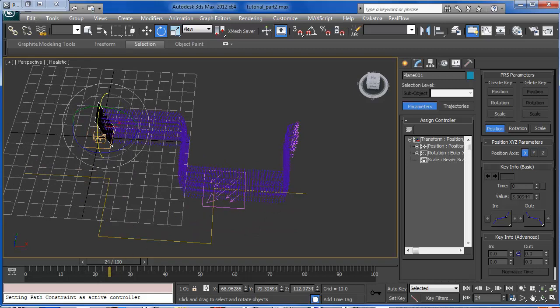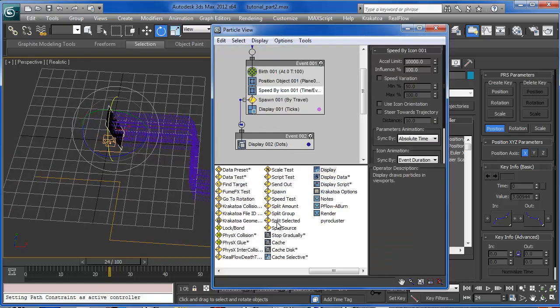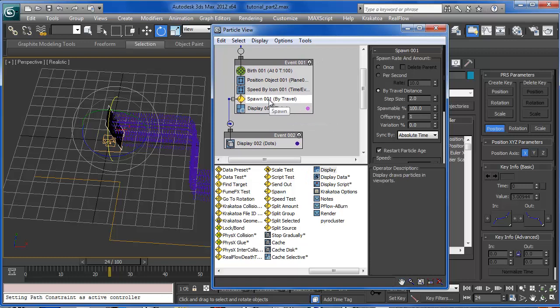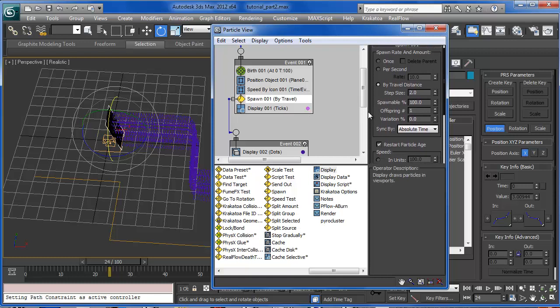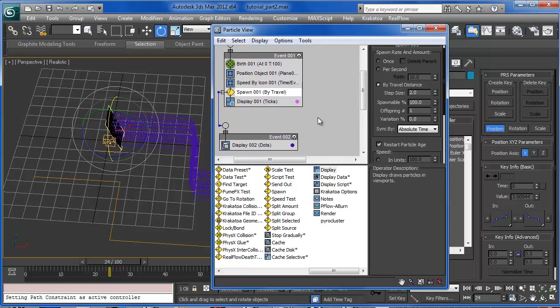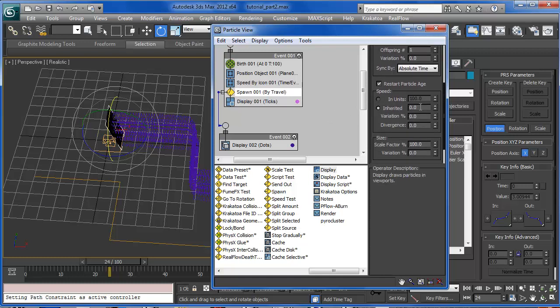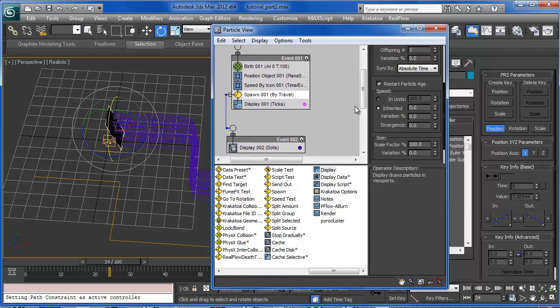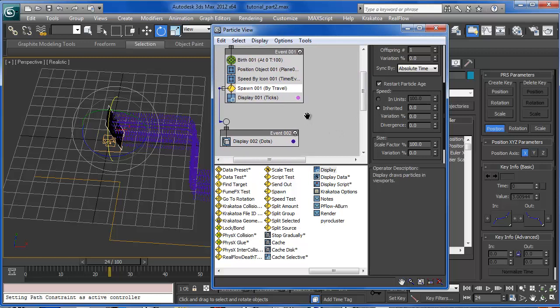Okay, so I told you earlier that we want to inherit a little bit. Why? Because we inherit the velocity, because later we will want to use motion blur, and motion blur needs velocity information. So if we set inherit velocity to 0, we will not have any direction, so we cannot multiply this vector by anything, because 0 multiplied by any number will be 0.